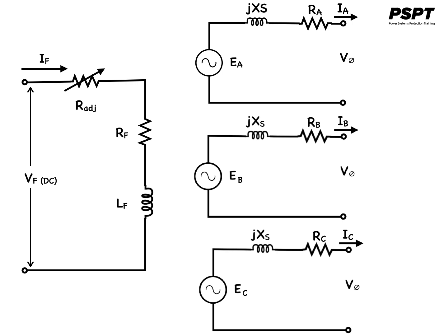The rest of the equivalent circuit consists of models for each phase. Each phase, A, B, C, has an internal generated voltage with a series inductance X subscript S consisting of the sum of the armature reaction and the coil's self-inductance, and a series resistance RA. The voltages and currents of the three phases are 120 degrees apart in angle, but otherwise the three phases are identical.